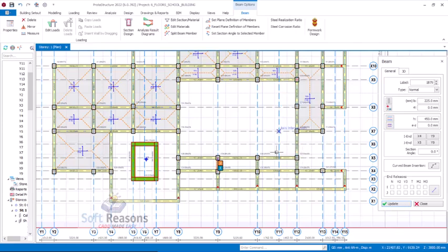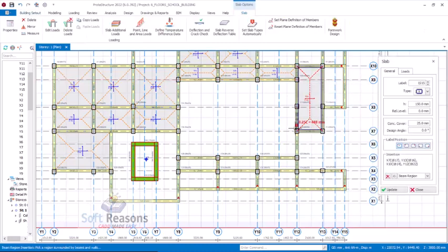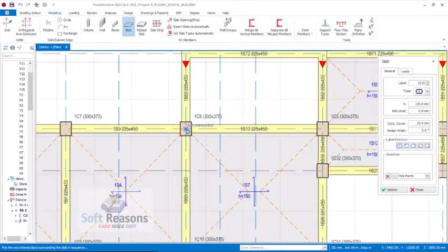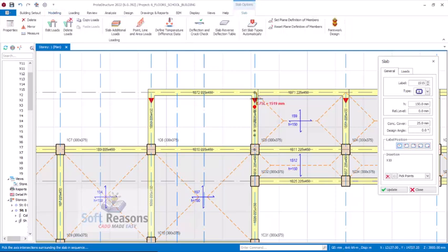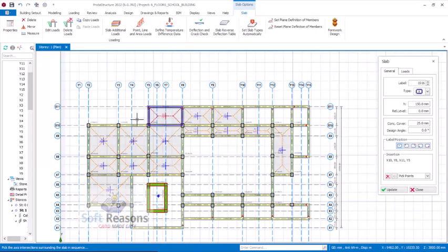Alright, so here we are having a kind of a cantilever slab here. So we will use the insertion point for the slab. Select this slab, already created, right click it properties. In the properties, we come over to these options, insertions. You can see beam region. So select this, and then we use pick point, or axis region. We use pick point. So we pick the first point, pick the second point, pick the third point, first point, to have this slab placed just like this.